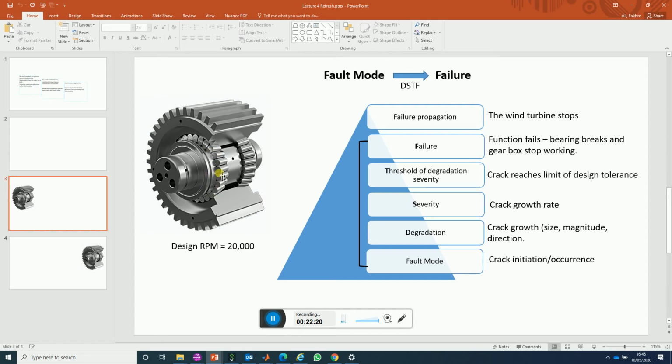What it leads to is what we call crack initiation. This crack initiation will expand the volume of this small bearing, and that can lead to, for example, a natural frequency that is above the natural frequency of the overall housing, and those can cause intolerable vibrations.